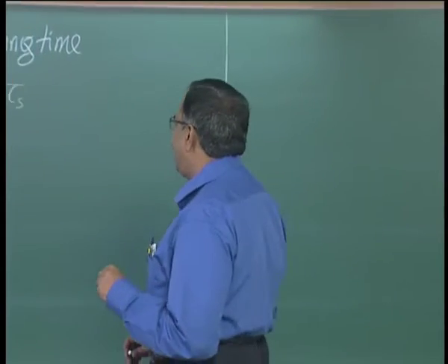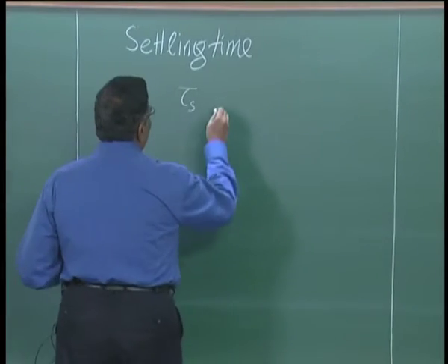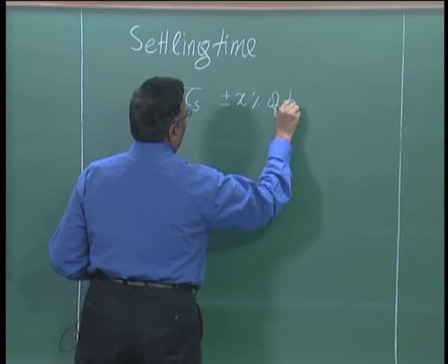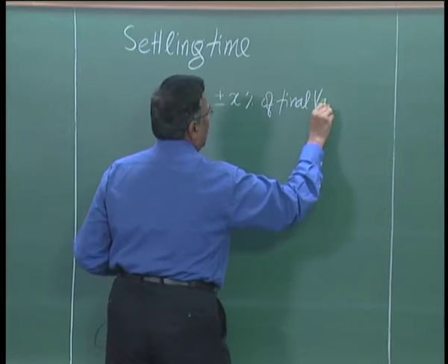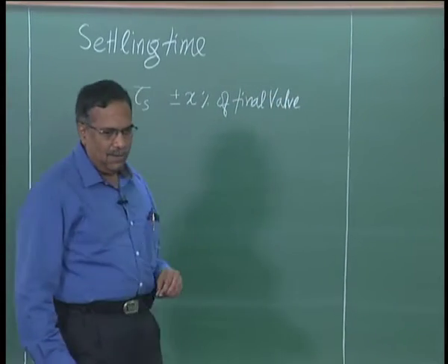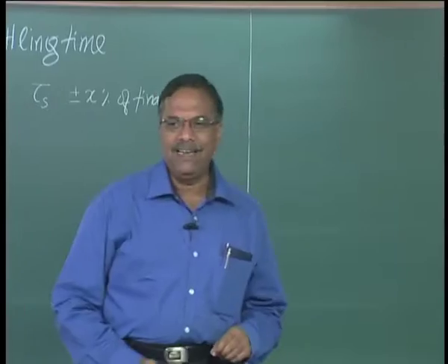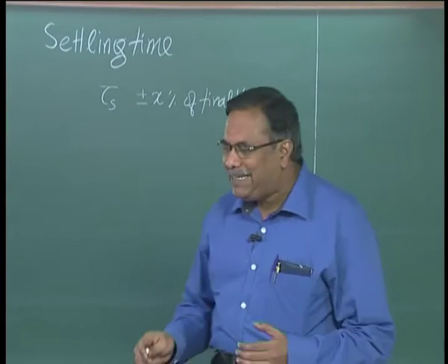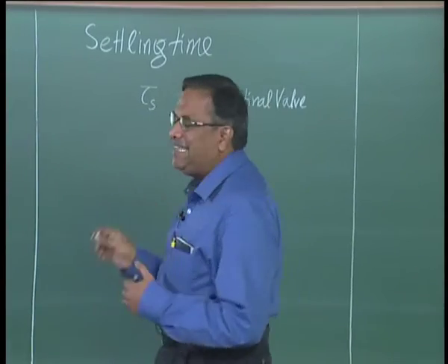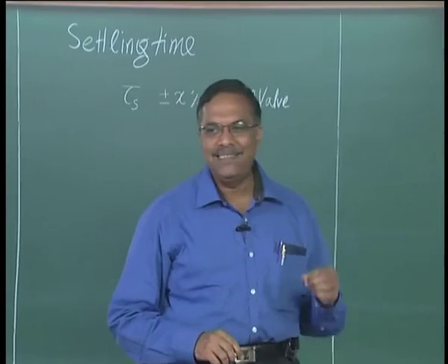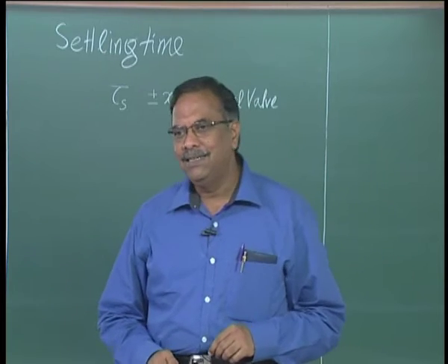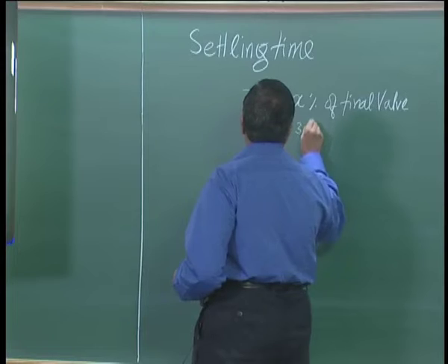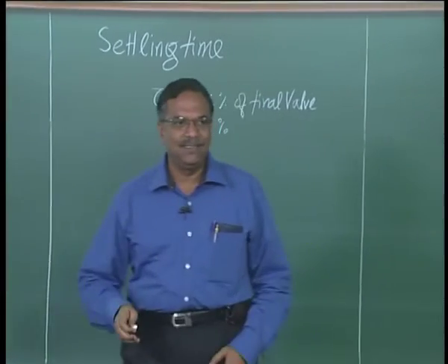So whenever I talk about settling time, I also have to say how much is the closeness that I can tolerate, because I can't wait for infinite time. So I can say that the meter goes to nearly this value that it has to indicate within a certain percentage, x percentage. Say within plus or minus 3% of the settling value, it takes 1.2 seconds, that is one value.